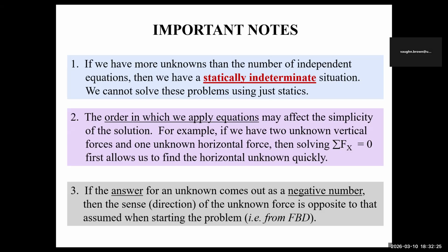The order in which we apply the equations may affect the simplicity of the solution. For example, if we have two unknown vertical forces and one unknown horizontal force. So it depends on the problem that you're solving. You will know how to apply the equation in number 2. I'll show you when we're doing trusses later on how number 2 really comes out. So it is telling you to look at your frame, and out of experience you know when to apply which equilibrium equation. That's what that one is saying.